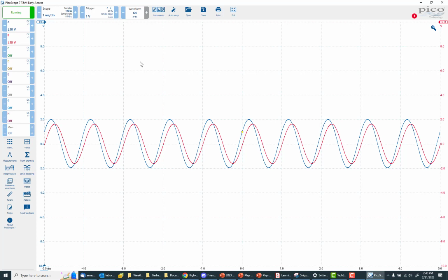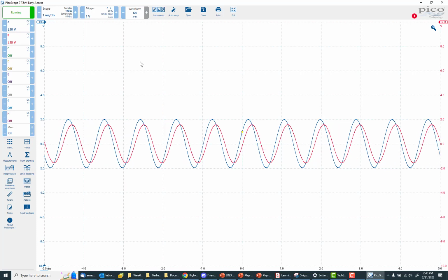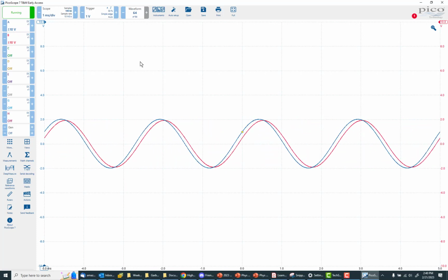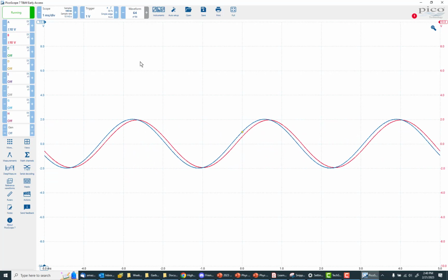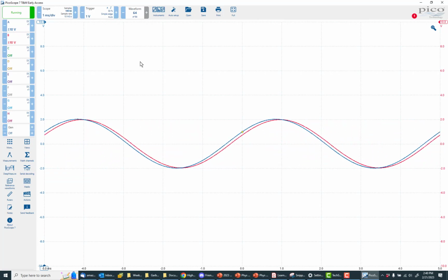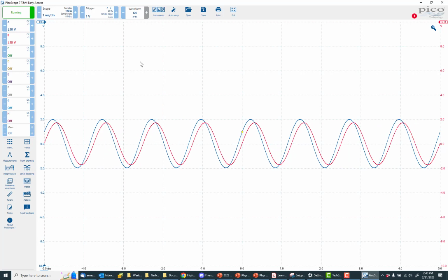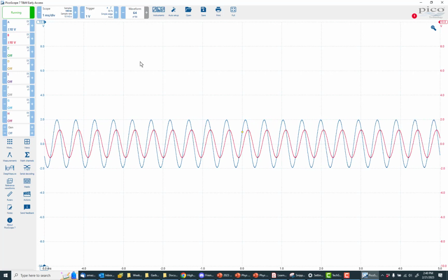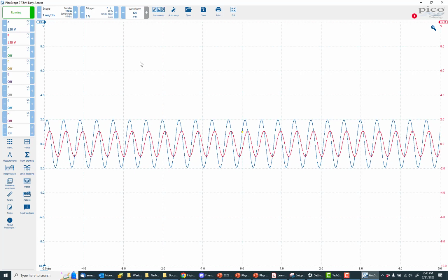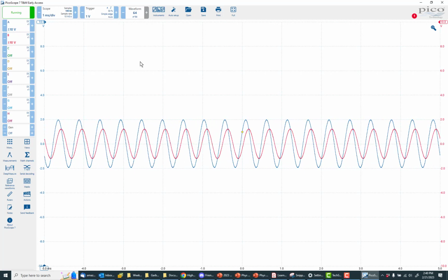So that means that it's not the current in the circuit. And so I'm going lower and lower, and the capacitor is higher and higher. It's a little counterintuitive because the resistor now has a very high Z and the phase shift is very small. That's simply because I'm measuring the voltage across the capacitor itself, which is something we do. And we just have to be a little clever to understand the phase shift.